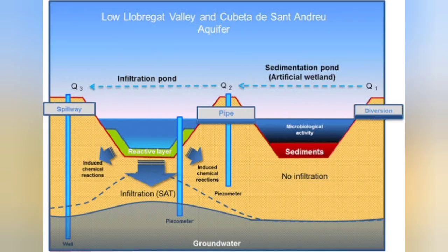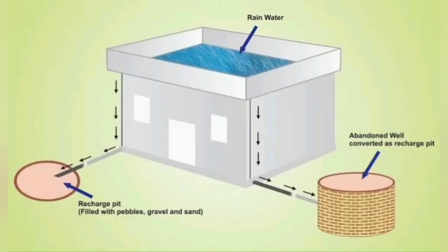The soil water conditions during the redistribution period are therefore those that primarily influence plant growth and agricultural husbandry, and that also provide the buffer action in the hydrologic cycle that the soil water zone has on the transport of water from the soil surface to the groundwater aquifer. As such, infiltration is critically interlinked with the phenomena of water movement in the vadose zone, which includes wetting front propagation.